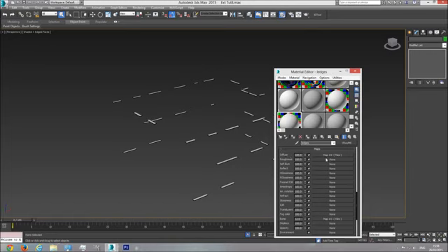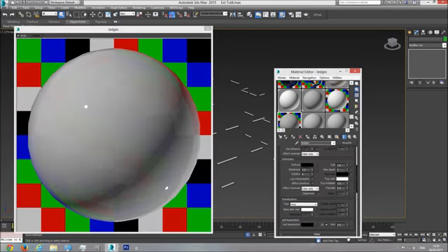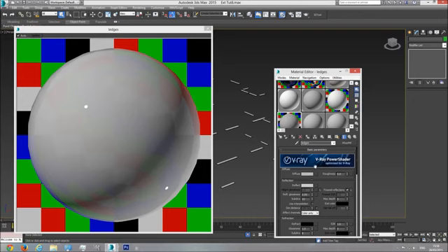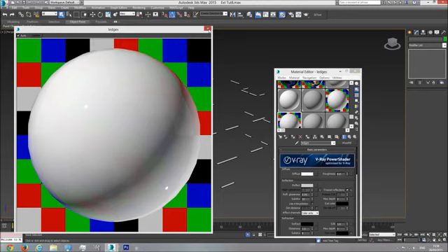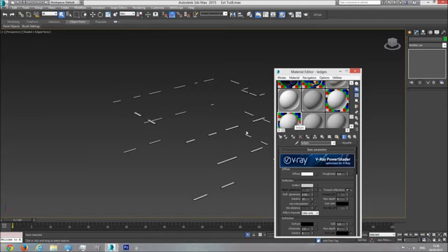I'm going to right click on the diffuse, clear, because I don't want the separations, and on the bump also clear. So now we have just a reflective gray material. So I want to change the gray color to almost white, something like 240. It's fine. That's going to be our ledge material, the white one.